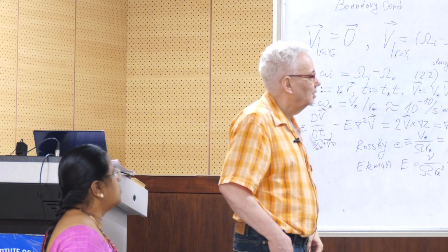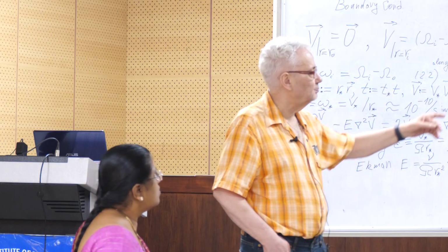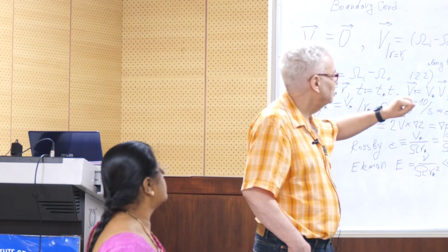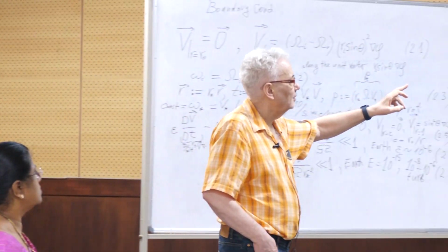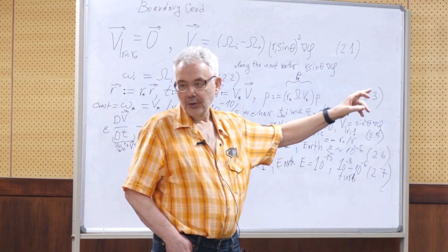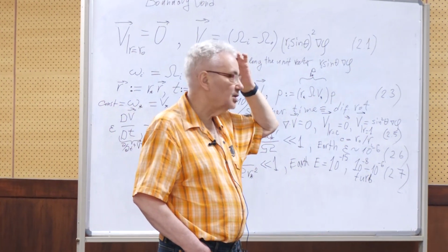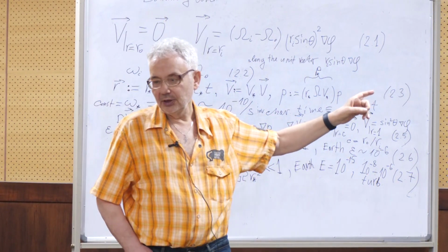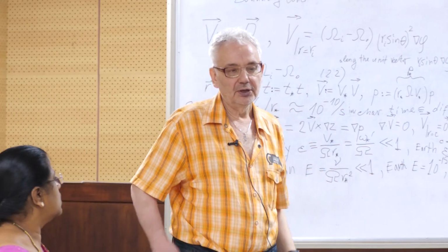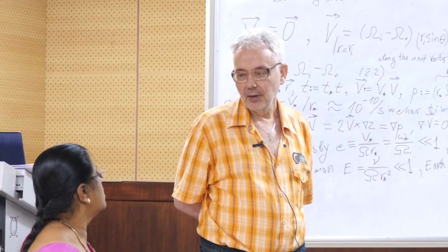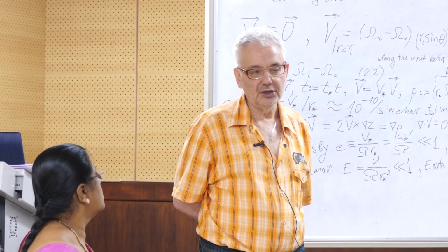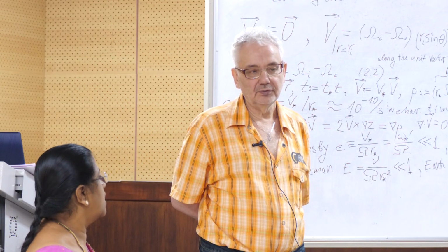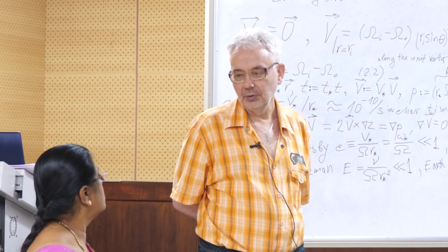But it comes as a surprise, perhaps the most important term in this case is the viscous term. One can think that because the viscous term is multiplied by a very small variable, a very small Ekman number, it's not important, but it's not true, because actually it contains the highest derivatives, and so we cannot omit it at all.